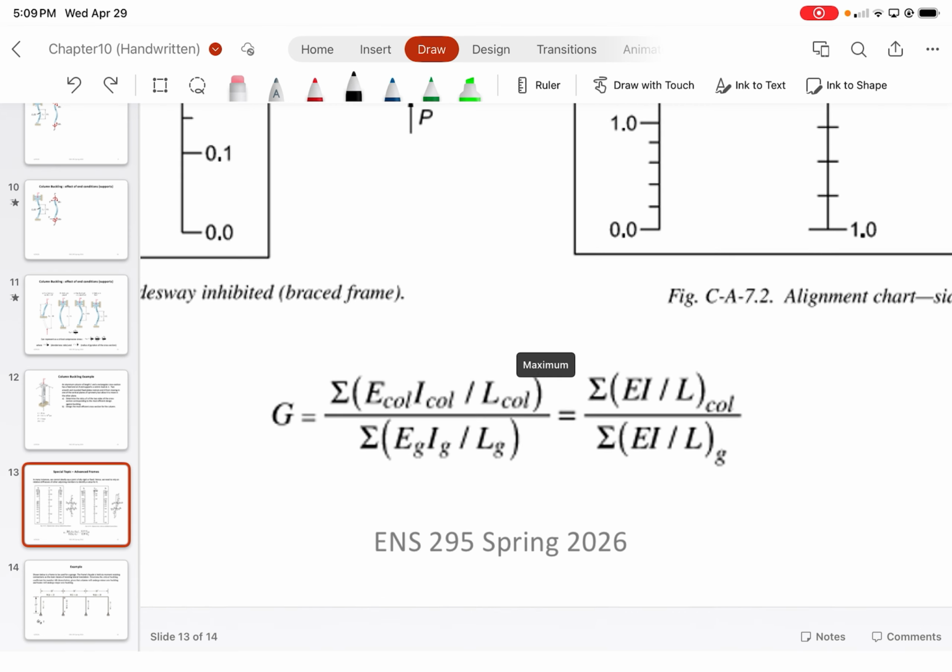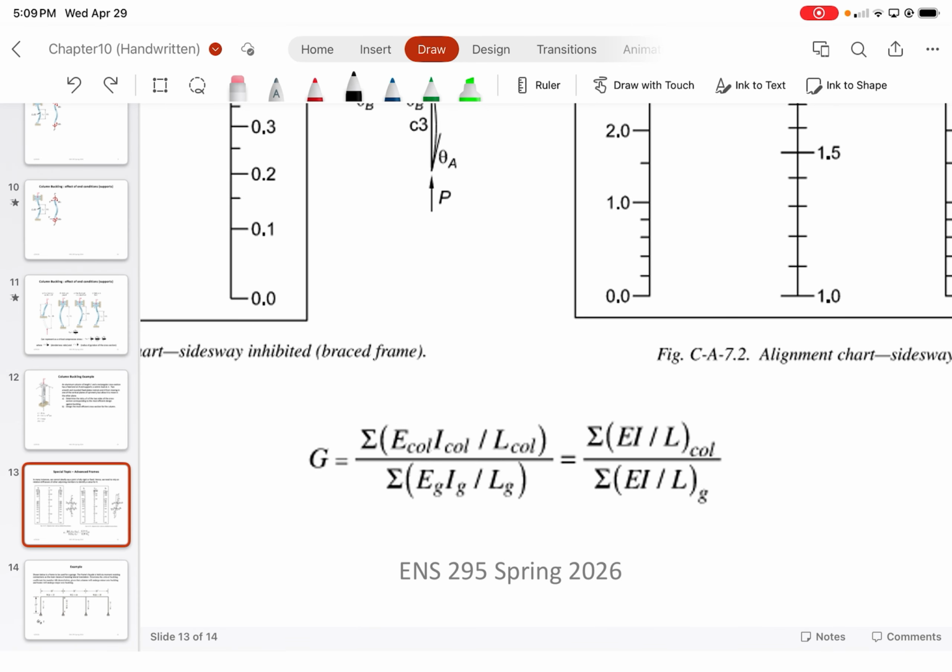Now, the G value, if you look carefully, is related to the elastic modulus times the second moment area of inertia divided by L. If you guys will notice, this is actually a flexural stiffness term, and this EI, which you guys have hopefully seen in a lot of the deflection equations, we call that flexural rigidity. That's just a general term.